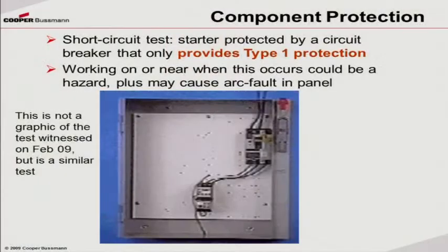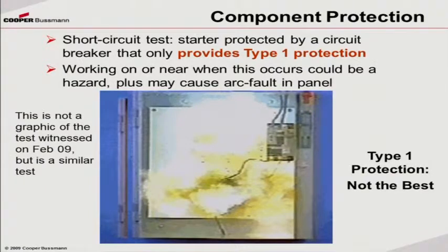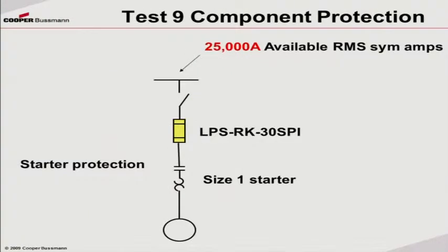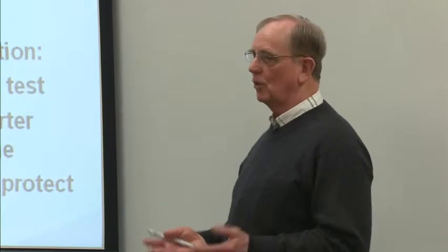Now the conductor feeding that would look like that during the fault current. With the current limiting device, nothing happens. So it's to the person's advantage that's working on a piece of equipment to be sure that it's rated so that they won't get that arc flash taking place in front of them.